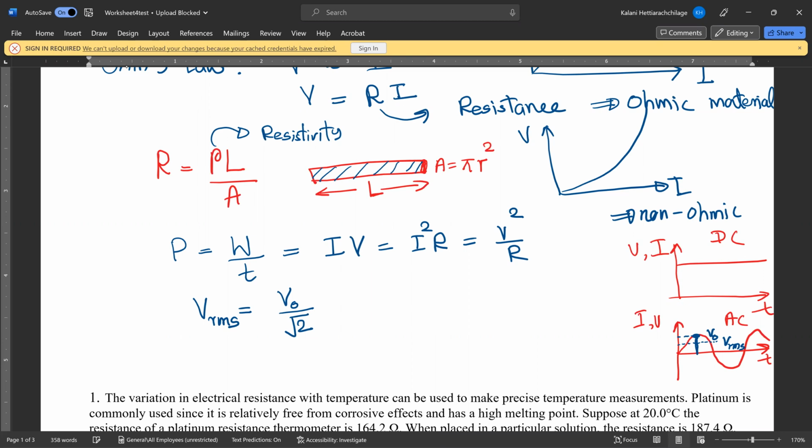We don't usually use an oscilloscope in your laboratory, but we will be able to see that whole wave, the voltage keeps changing with time, on the oscilloscope. The only thing you need to know is how these two connect to each other, and that what you are measuring in an AC signal is the V_RMS value, not the peak value.